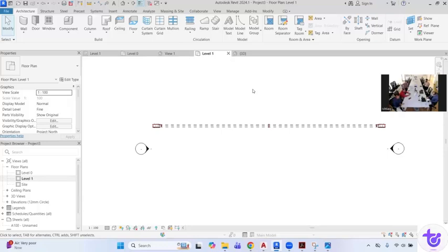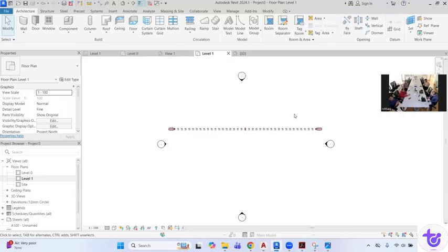But if you notice any in-place family, it will not fall under the view range category, because if any part of the in-place family is falling within the cut plane, it will show the entire family. I'm facing this with many of the families we create outside. Yes, this happens, mainly with the generic model and then converting to the category. It will show full. If we have 2 levels, there is no level constraint. That is something Revit doesn't allow.